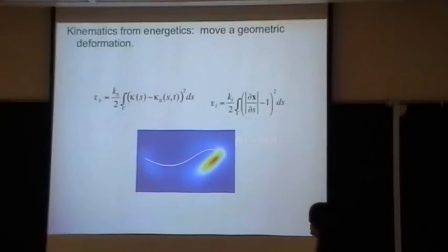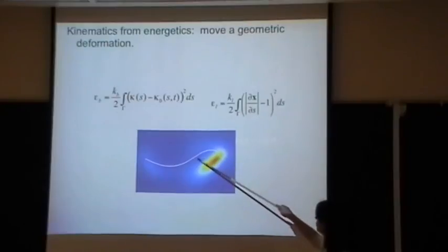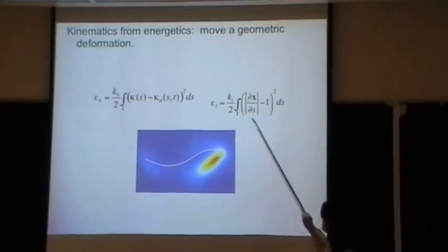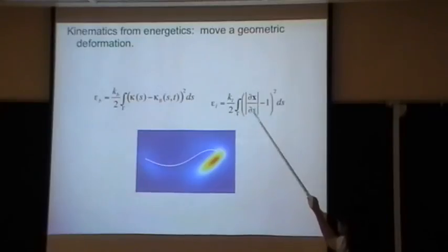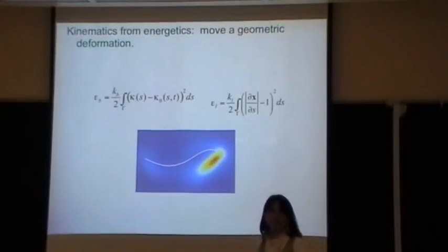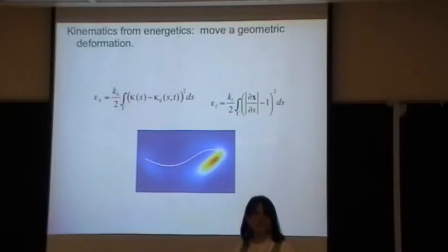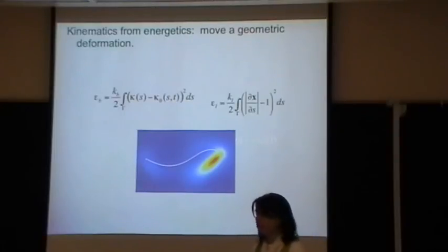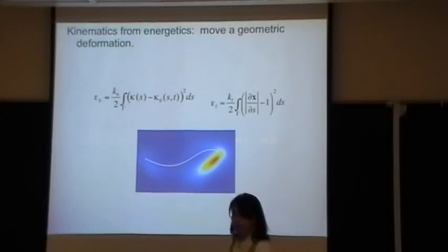Perhaps I should have looked at this first. When we think about wanting to model some filament by a bending energy where we're specifying a time-dependent curvature, and by some tensile energy where we're specifying the arc length, inherent in this formulation, and in most immersed boundary calculations, are these stiffness constants. You could think of them in two ways. You could think of them as numerical parameters that if you crank them up high enough, you will get the desired kinematics from putting in that prescribed curvature. Or, the better way to think of them, is as material quantities that tell you something about the passive elastic properties of your structure.